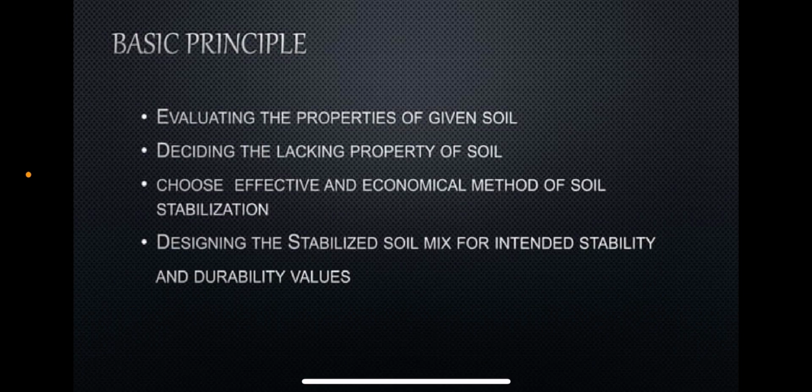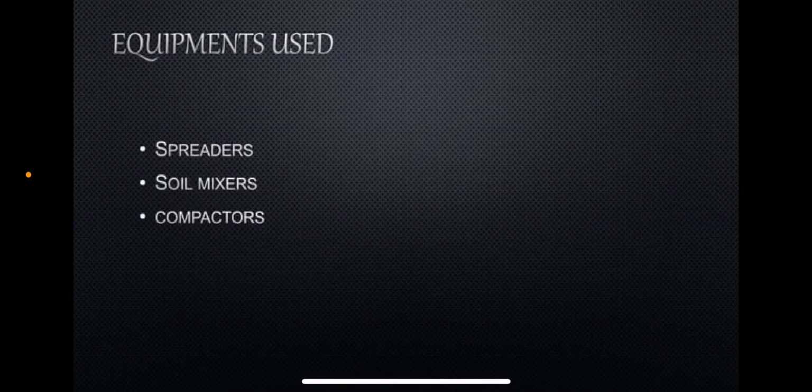And the basic principle: evaluating the properties of the given soil, deciding the lacking property of the soil, choosing an effective and economical method of soil stabilization, and designing the stabilized soil mix for intended stability and durability values.